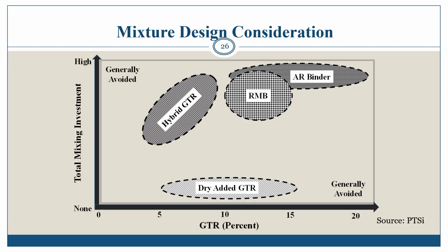Again, investment in this case is not necessarily monetary. Investment relates to GTR particle size, processing conditions such as agitation and mixing level, processing temperature, and processing time. Remember, generally smaller particle size processed at higher temperatures for longer times under higher shear conditions result in greater incorporation of GTR's performance properties into the asphalt mixture.